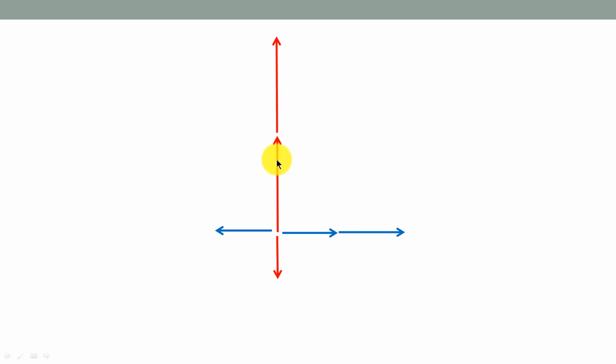But we have not yet found the actual resultant force in the direction PQ as we were required. We are in the process of doing that. Now, the next step is to look at the forces which are in opposite directions and they are equal in magnitude. For example, this is 5 newtons and this is 5 newtons. Because they are in opposite directions, naturally the resultant between this force and this force will be 0. So the only force which will be left will be this one, the 5.196 force.